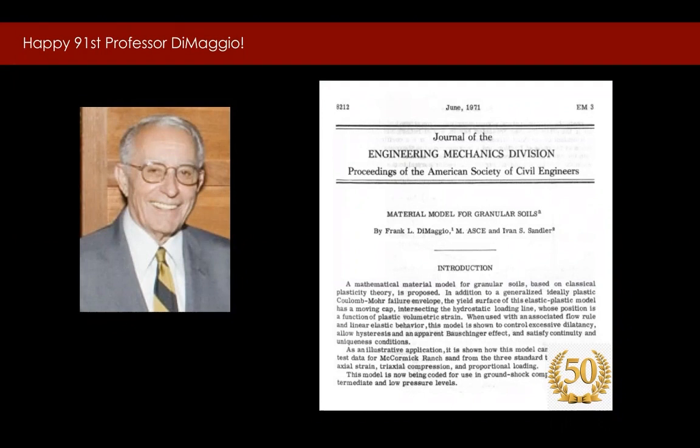Dr. DiMaggio's work was introduced to characterize the highly nonlinear behavior of geomaterials, including rock, soil, and concrete. The novelty with Dr. DiMaggio's plasticity formulation is a cap that can move under both compaction and dilation. This feature makes the model applicable not only to static loading, but also to dynamic conditions, such as earthquakes or an explosion. The movement of the cap is now understood to be a result of hardening or softening, induced by compaction or dilation. At that time, such an advanced model would not be practical for manual calculations.